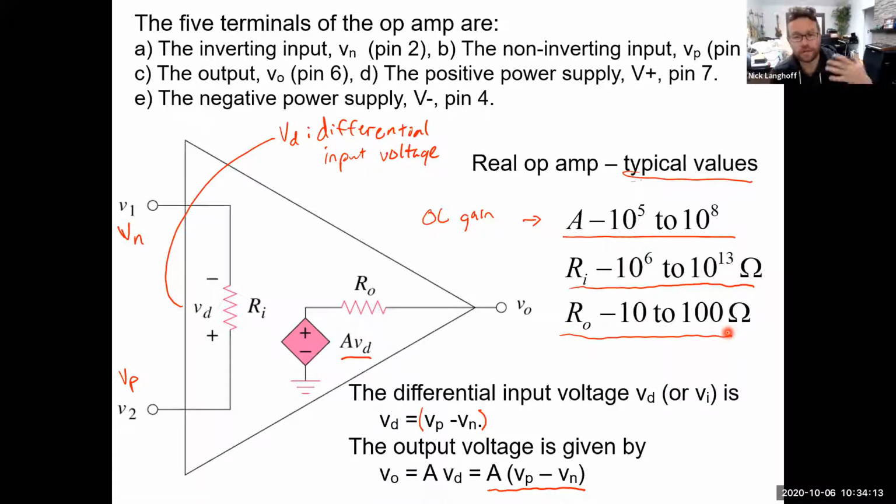I'm going to continue to use that word instead of resistance for two reasons. One, we're going to start to talk about AC resistance, in other words, impedance, as we move into the next segments of the course in the coming weeks. And so I want us to get more familiar with the idea of impedance. The units of impedance are ohms. When you're talking about amplifiers, a lot of times amplifiers are used with AC signals, so they aren't DC signals driving them. And so the resistances aren't just resistances.